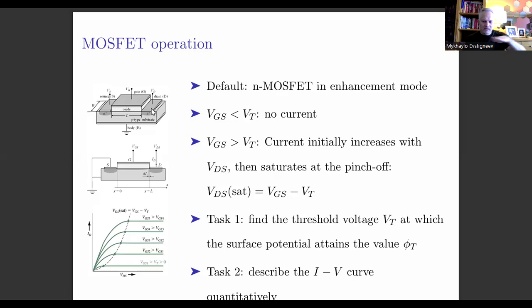Instead, that metal electrode, that gate electrode, is deposited on a thin, how thin, maybe a few hundred nanometers layer of a dielectric, which is usually an oxide. So usually these MOSFETs are silicon devices, and the most logical material for the dielectric would be silicon oxide, right? Because what else? That's smart, right? You can oxidize silicon very easily. All right, so that's your MOSFET.